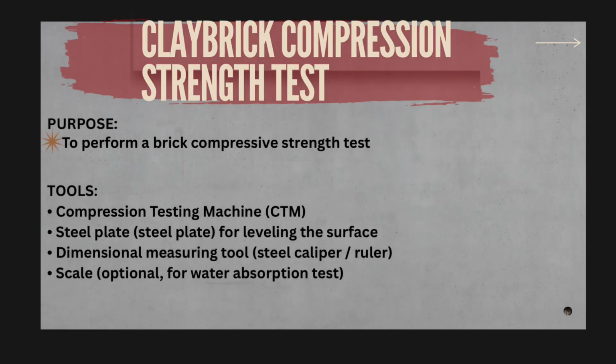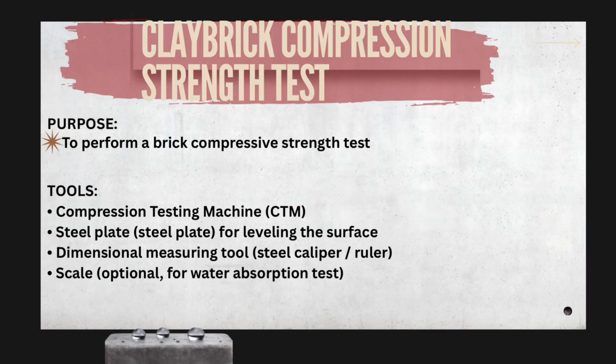Clay brick compressive strength test. Purpose: to perform a brick compressive strength test. Tools: compression testing machine (CTM), steel plate for leveling the surface, dimensional measuring tool, scale.